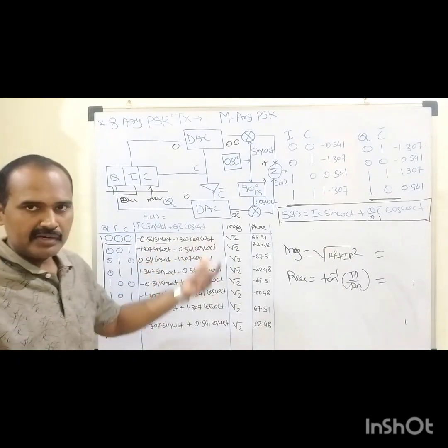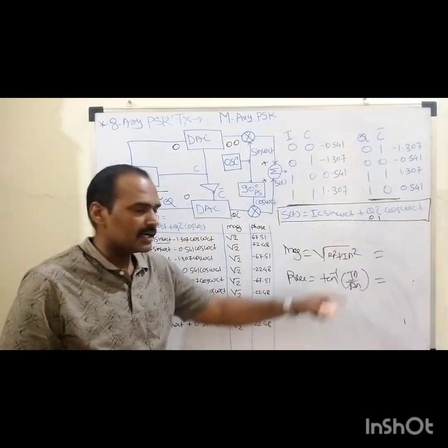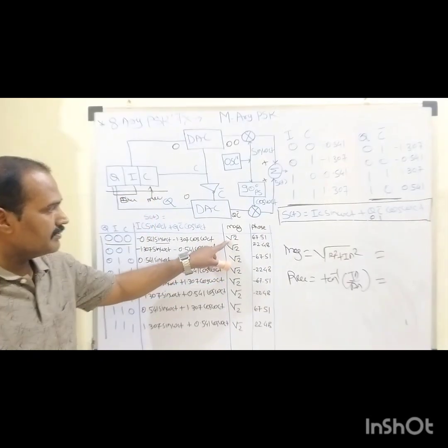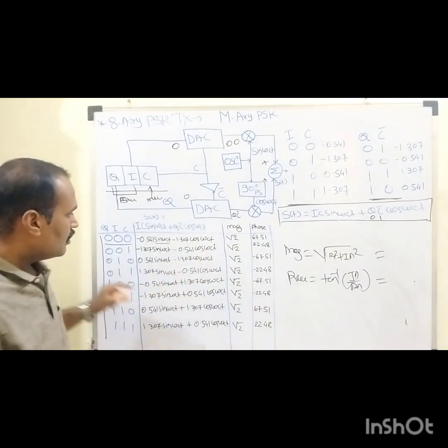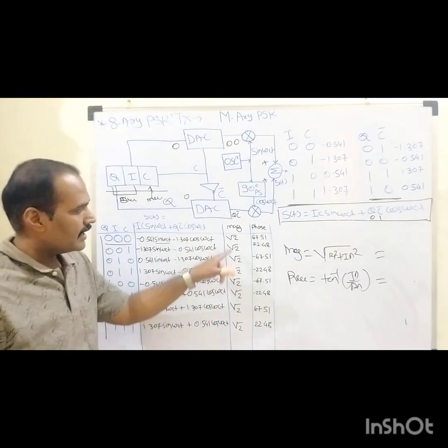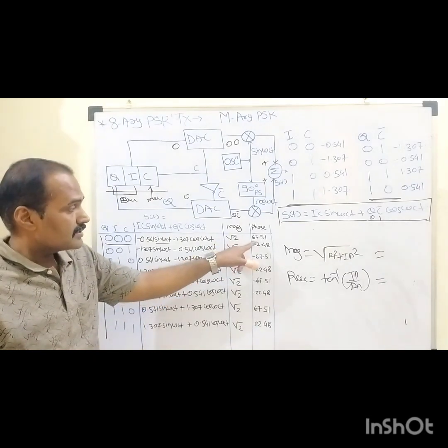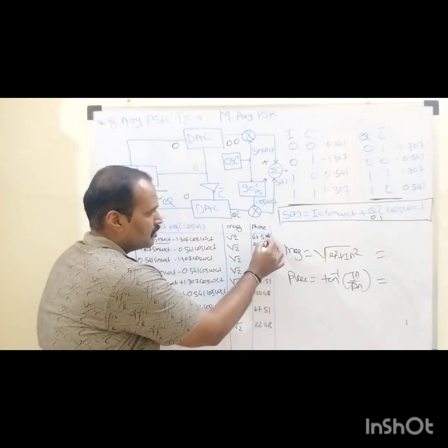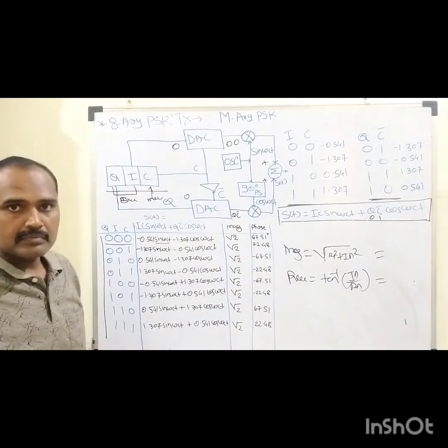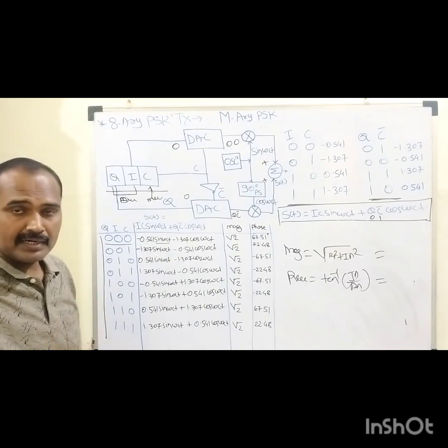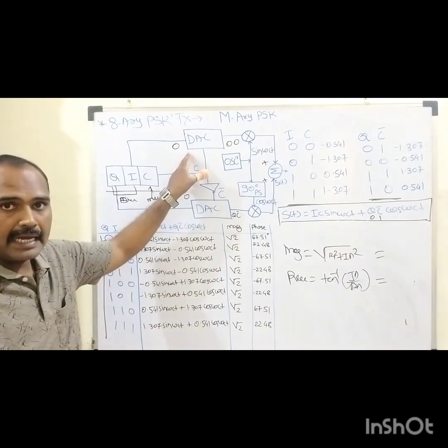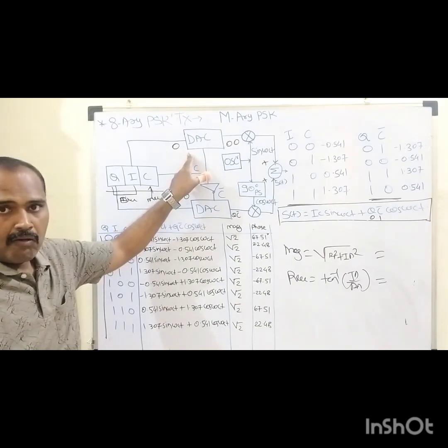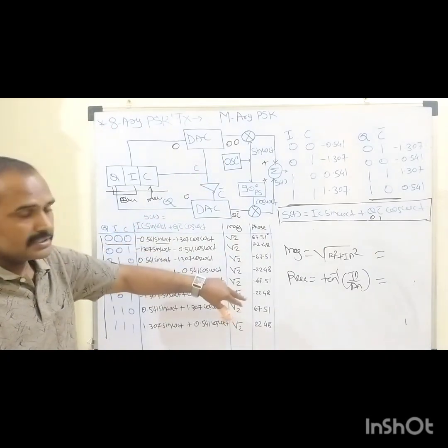When we substitute the desired values of the real part as well as the imaginary part, or the in-phase channel and the quadrature phase channel, we will come to know that the magnitude of this modulated symbol is exactly root 2, right? And its phase angle is almost 67.51 degrees. So by an amount of 67.51 degrees, the phase of the unmodulated carrier signal is changed by this 8-ary PSK modulator, or the 8-ary PSK transmitter, right? So this is how this system works.